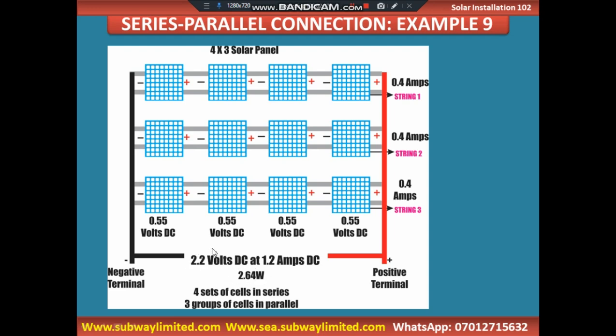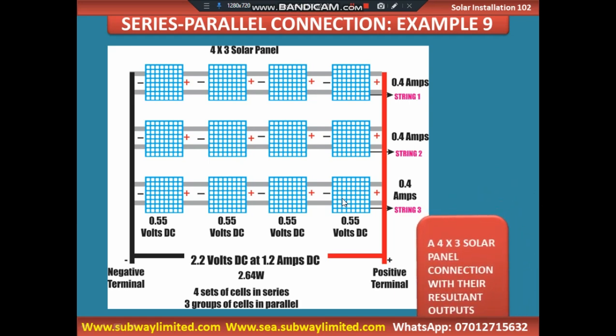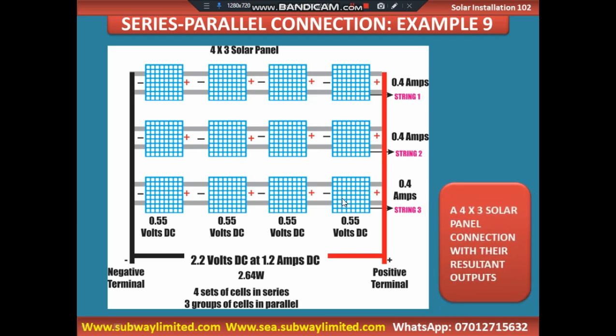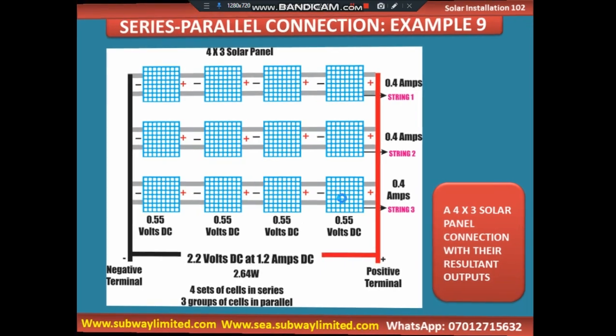If you test it with your multimeter, 4 sets of cells in series, 1, 2, 3, 4. That is 4 sets in series. 3 groups of cells in parallel. String 1, string 2, string 3. That is what you have if you connect such panel in series and in parallel.